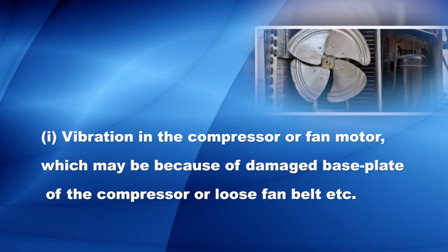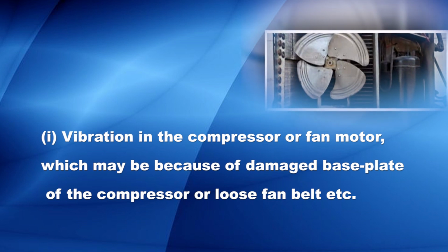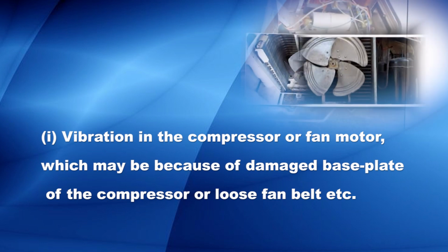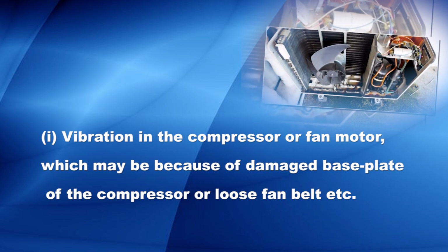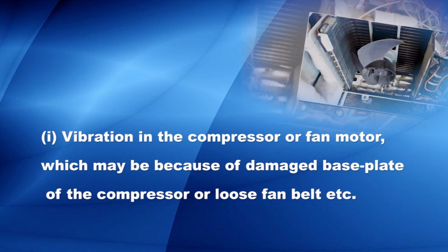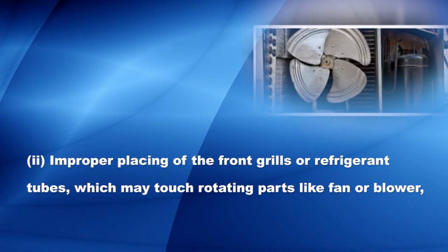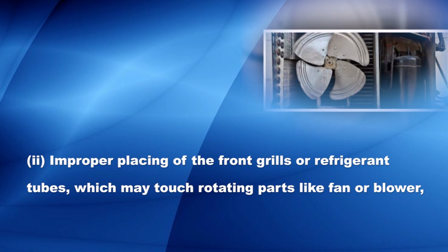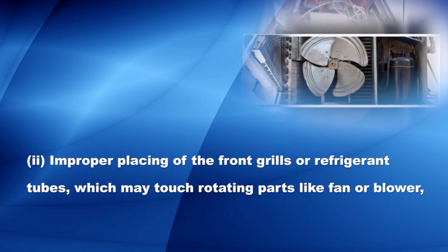The next issue may be the noise. The noise may be due to the vibration of the compressor or fan motor, which may be because of the damaged base plate of the compressor and the loose fan belt, etc. Improper placing of the front grills or refrigerant tubes, which may touch rotating parts like the fan or blower. Next is the damaged cabinet or loose bolts and nuts.